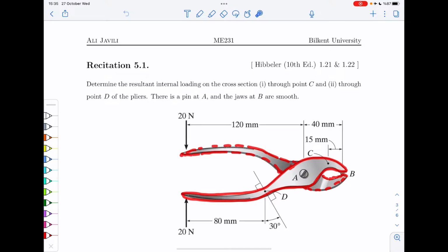And you can imagine it's basically a symmetric problem, so we can analyze each of the 2 pieces, right? But if you analyze the piece on top, so if you look at this one, you would have a force from the pin at A to the top part, or to the part in front of us, which the opposite of that would be applied to the part behind.